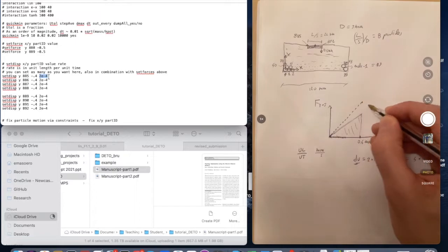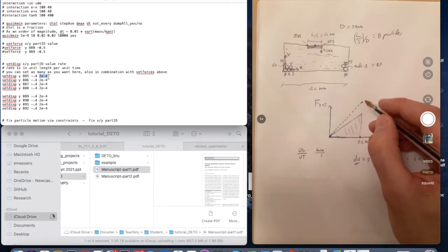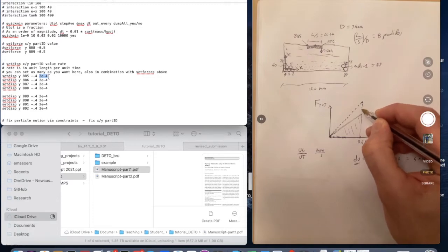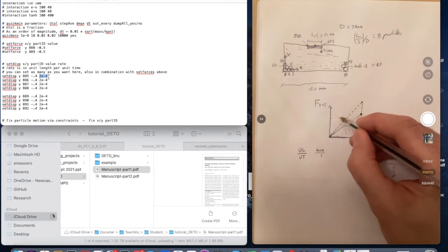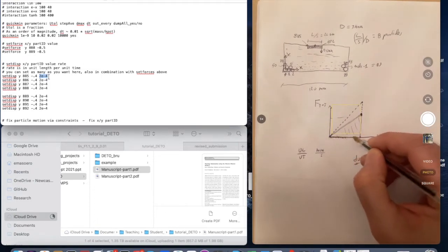You will overshoot it. But then you will notice that the minimizer will realize that you overshot, and when you reach the imposed displacement, instead of stopping, it will actually continue relaxing until going back to the correct force displacement solution. And once it knows this position, it is able to reconstruct correctly the strain energy under the curve.